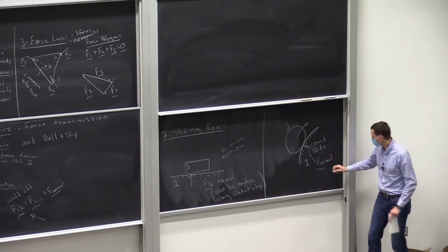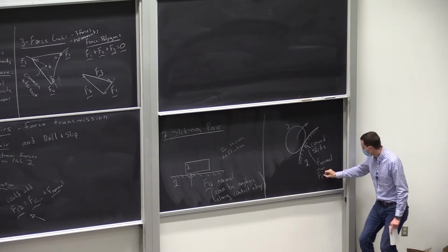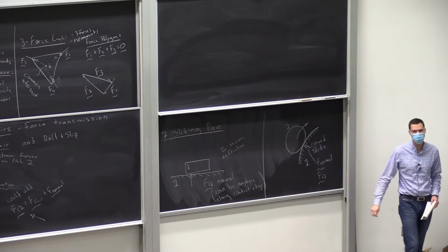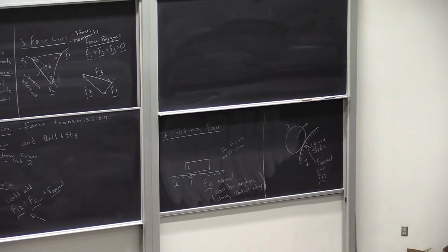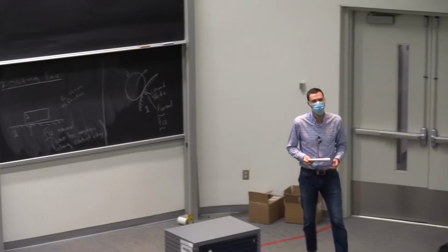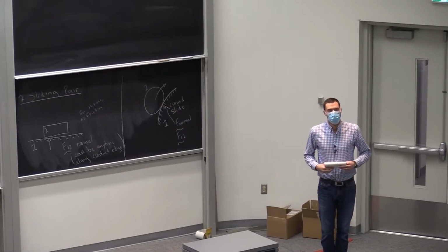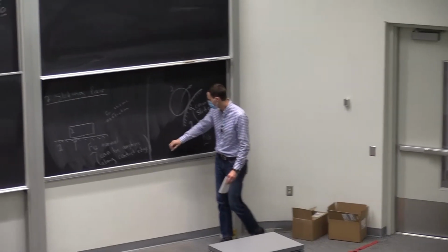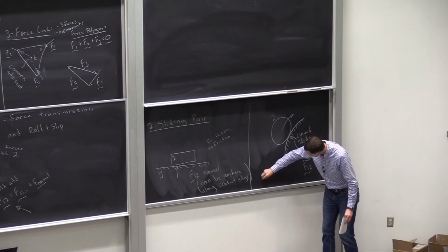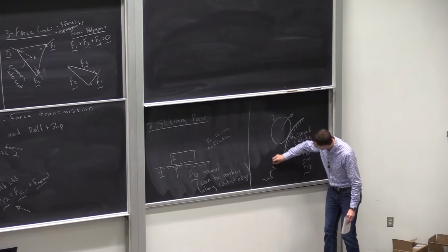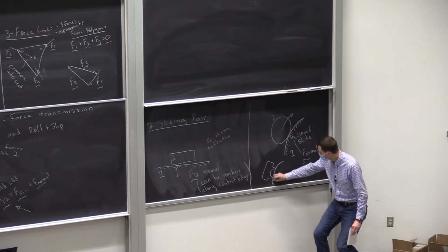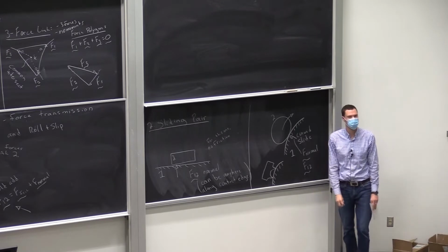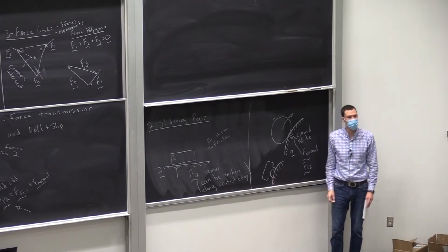And that would be the force from 1 onto 2. That's what I've drawn there. Yeah, do you have a question? Yeah, so would this only apply to just one contact point? Because if there's multiple contact points, then there technically would be normal force in different places. Yeah, if there were 2 contact points, let me just draw a link like that, 2 contact points, then yeah, you said it could be anywhere between them.